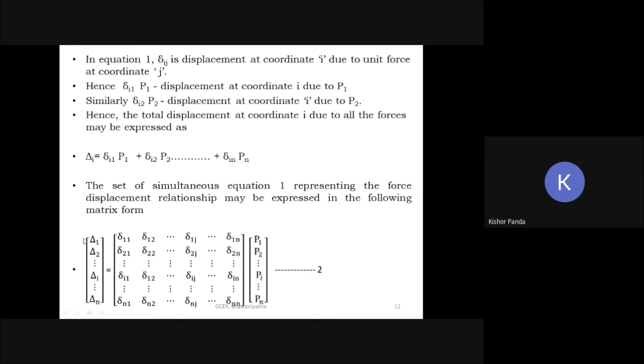So if you know the flexibility matrix and the forces acting at different coordinates, you can find out the displacement at different coordinates using this matrix.